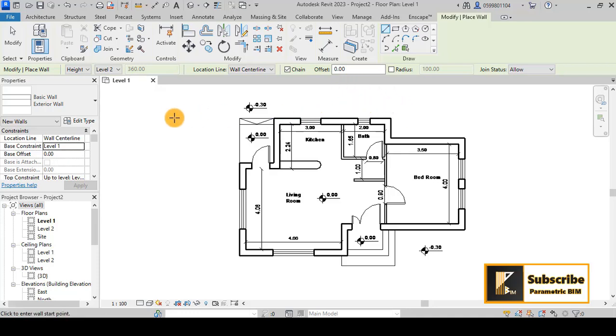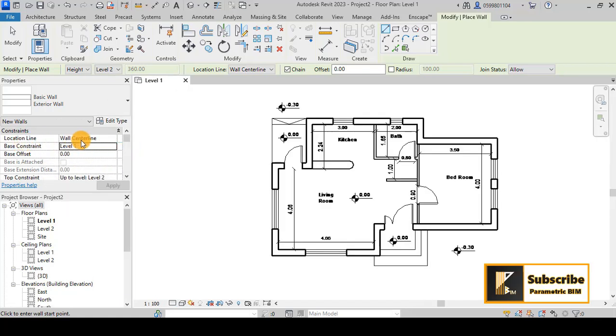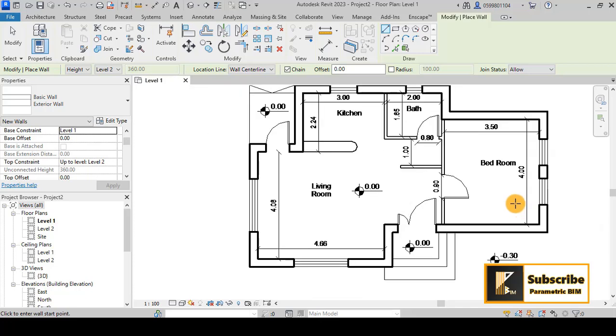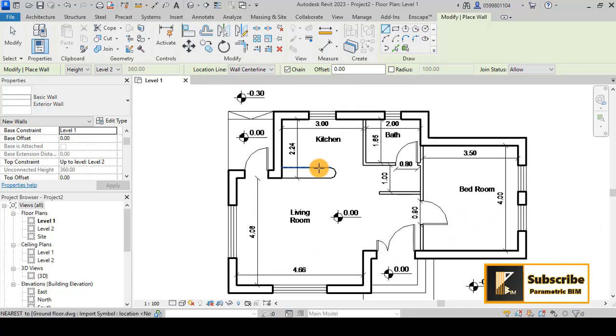Once I click here, I will have the opportunity to choose where these walls start, from level 1 to level 2. It will give me that as a default, so it is okay for me. And I will now try to draw over these walls from level 1 to level 2. But if you have other plans, such as first floor plans, you have to play with that and add levels as you want.